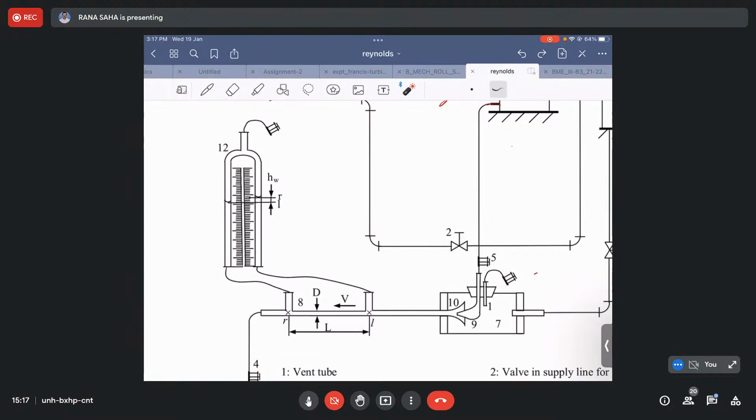Okay. Here, the tube is horizontal, so we have to ensure the tube is horizontal, so there is no elevation head reflected in the manometer. How can that be ensured, that it is perfectly horizontally mounted? For that you need some kind of spirit level to be placed, and then check whether at different points the pipe shows the same reading of the spirit level. So to ensure the pipe is horizontal. If it is horizontal, the head difference will only be the head loss due to friction.